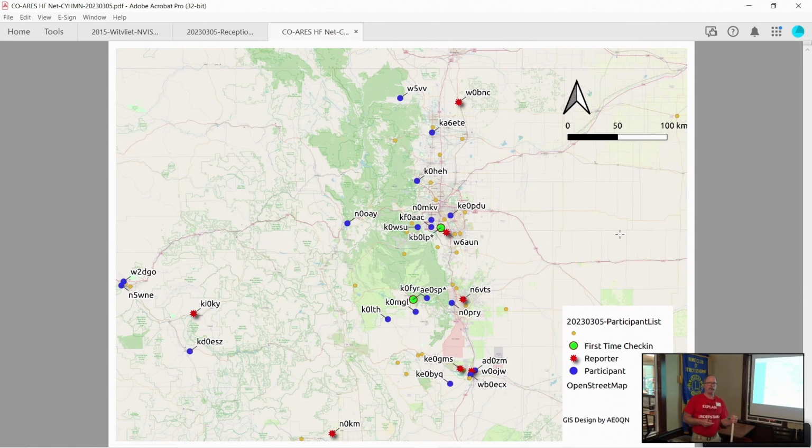At my house, that's what I have, 84 feet long at 15 feet with a 33-foot counterpoise coming down and a 9-to-1 balun at the feed point. Why a 33-foot long counterpoise? Because I had a 33-foot piece of wire from a 40 meter vertical. So I had one.